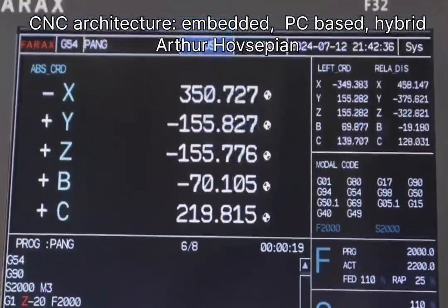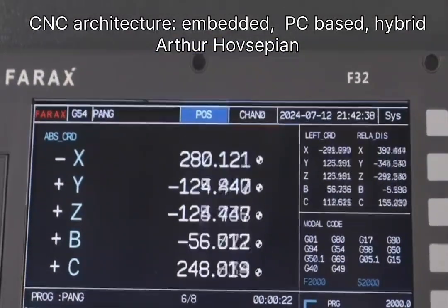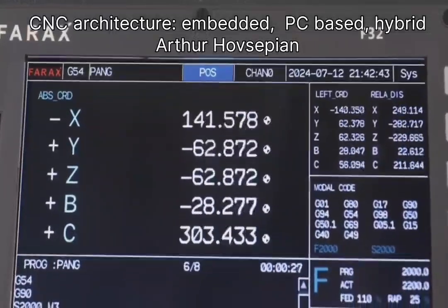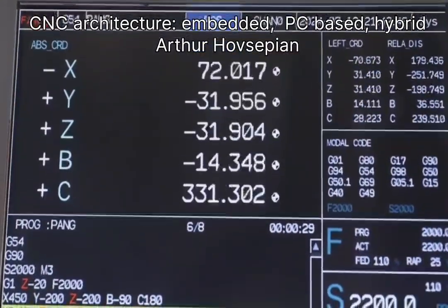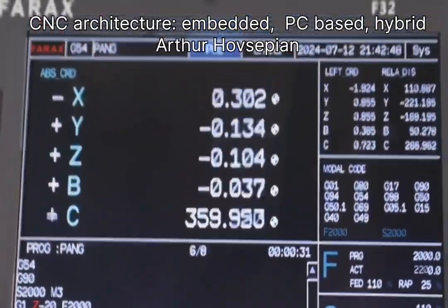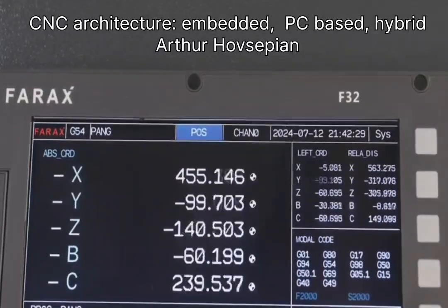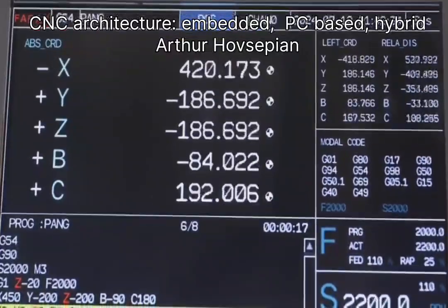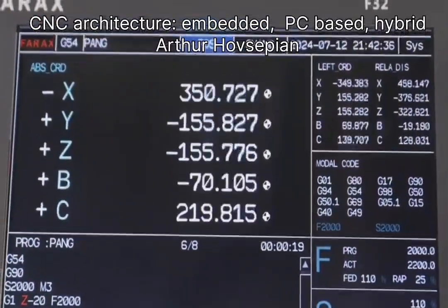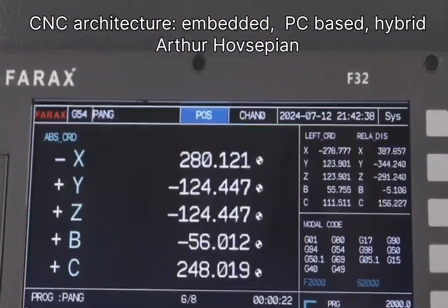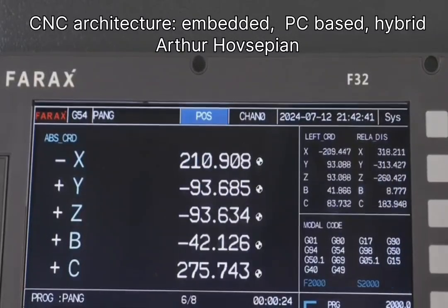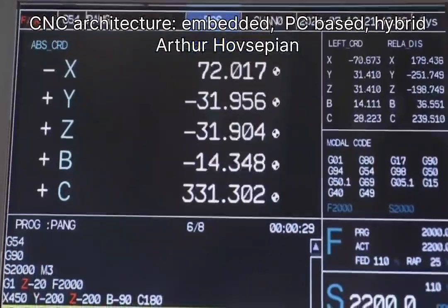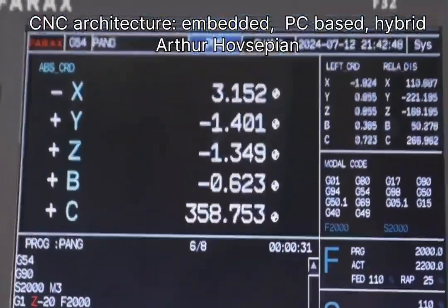So looking ahead, where are things going? What's the future look like for CNC controller architecture? Are new technologies changing the landscape? Oh, definitely. Things are moving fast. We're seeing much more integration of advanced tech. Think powerful multi-core processors, a wider use of those FPGAs for custom processing right in the hardware. More power, basically. More power, yes, but also more integration. Systems on chip, or SoCs, are becoming more common, packing lots of different hardware and software functions onto a single chip. This lets controllers handle more complex tasks simultaneously, faster, and more accurately. They're getting smarter, not just faster.